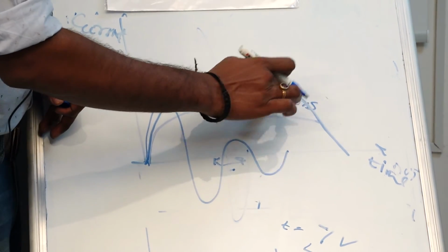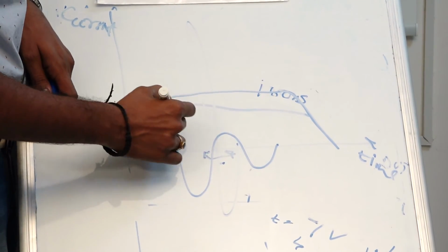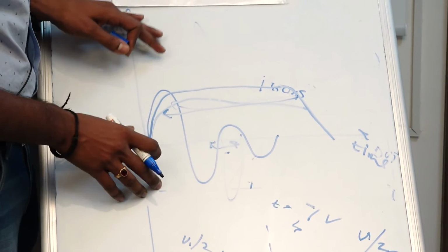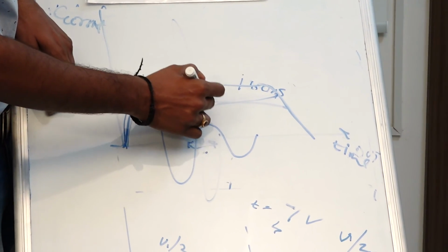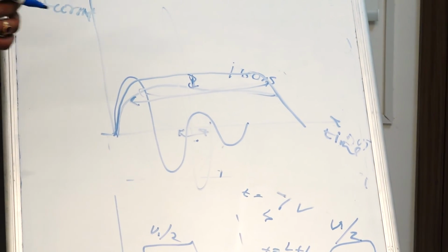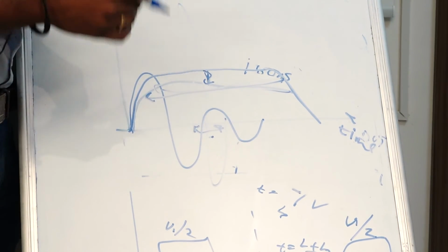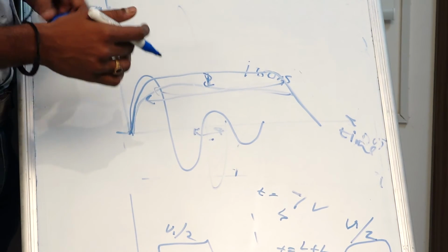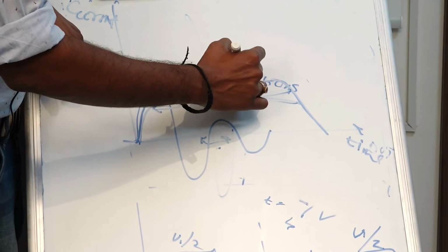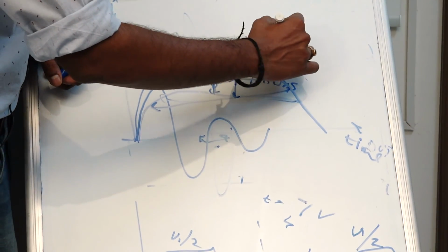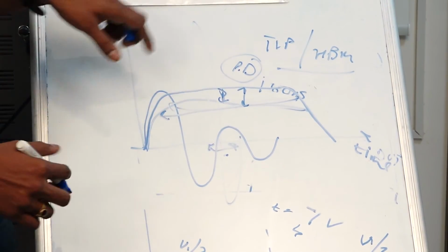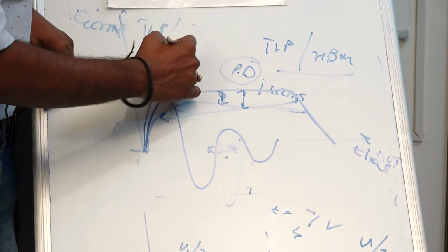So the important thing is, by changing the pulse width of the TLP generator, you could emulate to some extent different ESD models. HBM is easier to do because HBM also has a somewhat rectangular shape, although it's decaying in nature, but it has somewhat similar shapes. So the amount of heating and the amount of power dissipated between the TLP and HBM are somewhat similar. This is, however, not the case in other models.